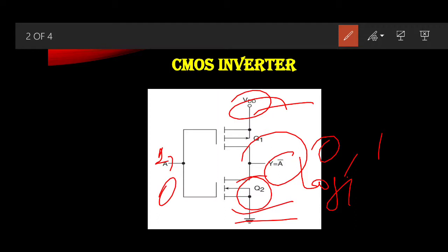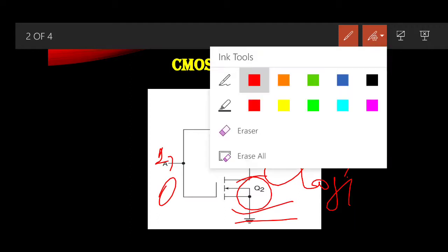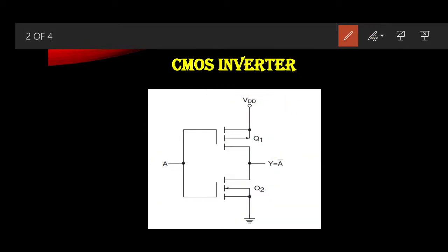There is only dynamic power dissipation, which occurs during the switching operations as the MOSFET gate capacitance is charged and discharged. So the power dissipated is directly proportional to the switching frequency. It is completely dependent upon the switching frequency.